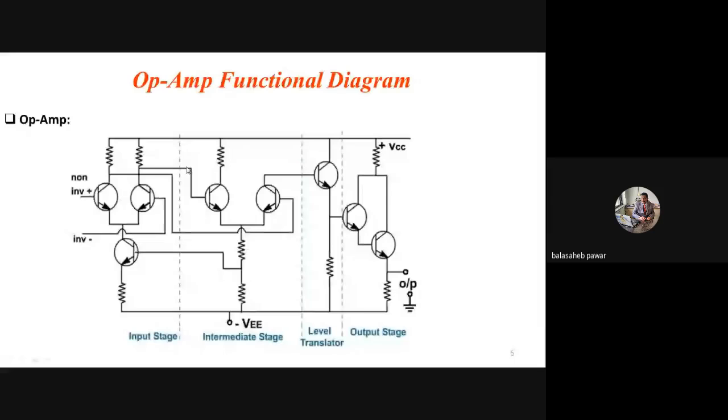Okay, and that's why it is known as a balanced output. Output is taken out from the collector of both transistors. What is meant by dual input and balanced output? Such a type of configuration is known as a differential amplifier, and that's why that word is common, that is, dual input balanced output differential amplifier.